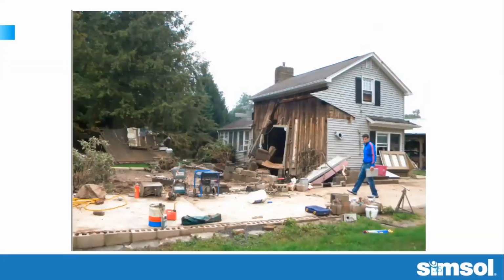Now this is a good example. Take a look at this one, study it for a second. We've got some siding missing on the back side of the house, but we have no shingles missing on the second floor roof. You've got something going on back there to the left that's stuck up in the pine trees a little bit, and it looks like the block wall or somewhat of a wall footing there in the foreground. I can tell you that this building was damaged by flood.